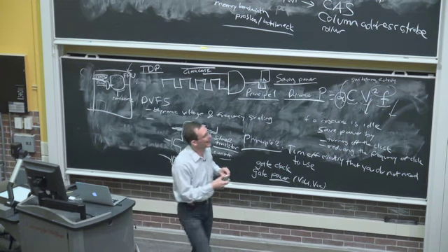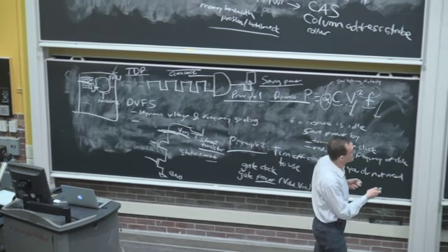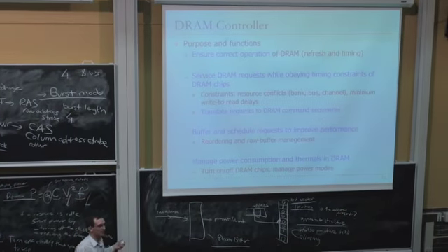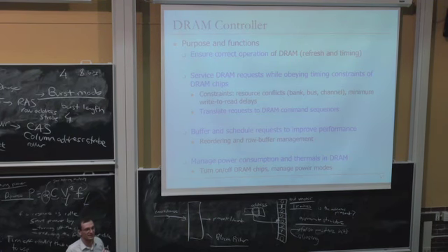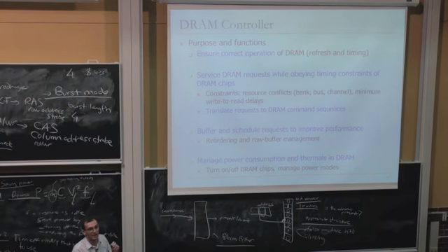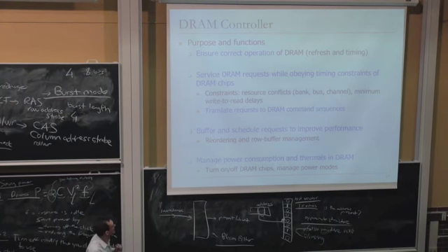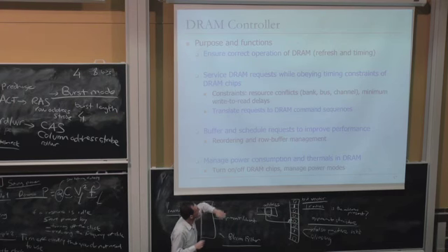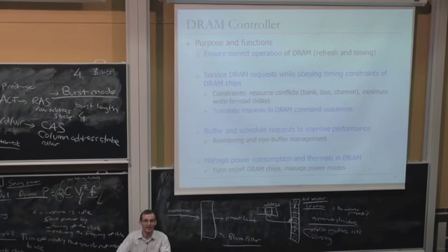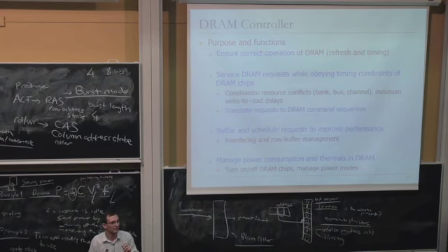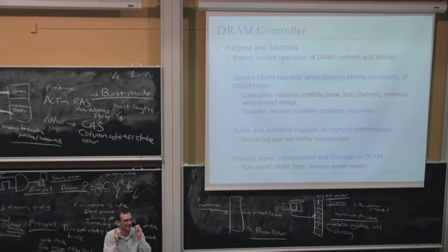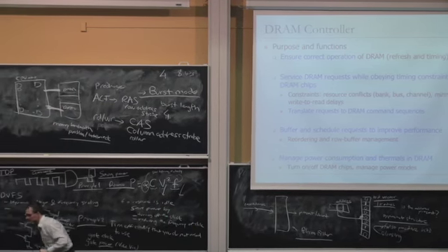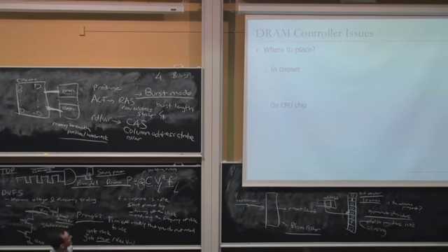So let's get back to the DRAM case. Some DRAM chip, you're not using it for some reason. The data is not mapped to it. Right? You can turn it off, right, to save both dynamic and static power. The downside, when you need it, when you need to allocate data to that particular chip, now you need to turn it back on. And that takes time. Okay?